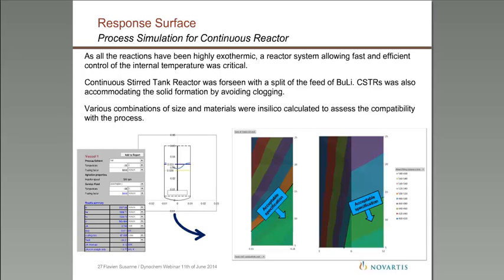And knowing that, from this we will have an input, and from then we can do the heat balance. We'll have an input, which will be the enthalpy of reaction, and we will have the output, which will be the heat which can be withdrawn by the reactor to maintain the temperature at the set point plus or minus 5%, being our acceptable range.